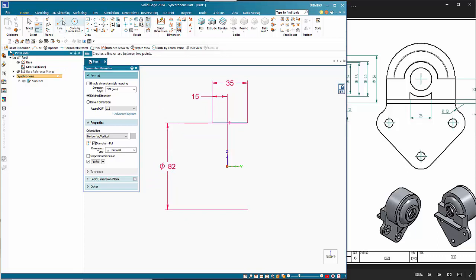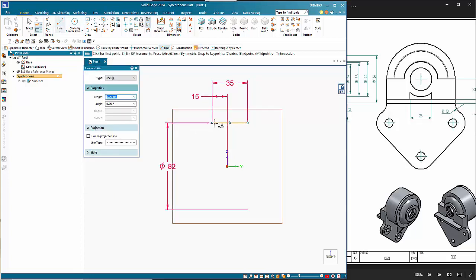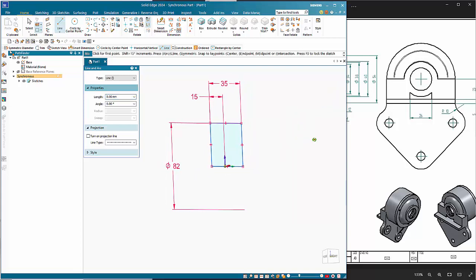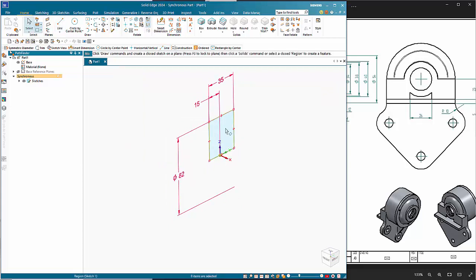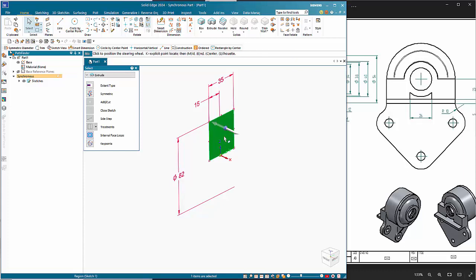So as I said, I'll revolve this, so we'll just come in. So just hover over the plane to get that coordinate system. I've got the vertical indicator on there, and likewise you'll see that this one picks up. If you don't see it, you just move over the endpoint and pick that, and we can close that off, and that creates a closed profile.